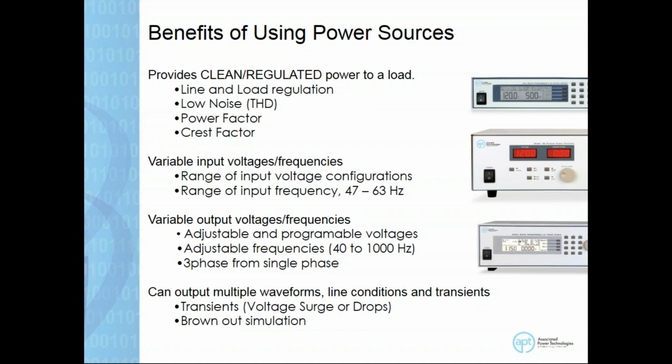Some of the requirements for airplane applications or any kind of avionics applications may be 400 hertz, because the power requirements for those applications may be 400 hertz, 800 hertz. So these are typical benefits you get taking in 60 hertz input and providing 400 hertz, 800 hertz, up to 1,000 hertz of output from the same supply.